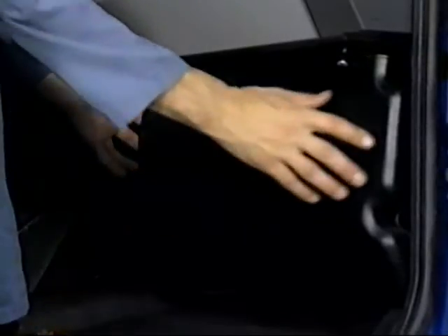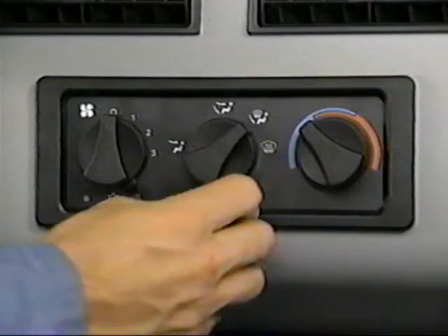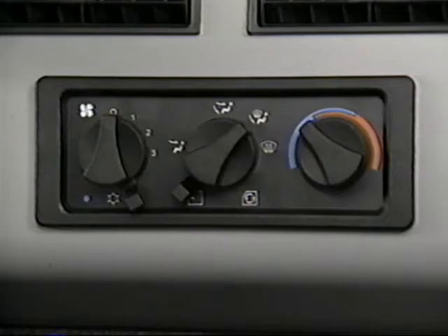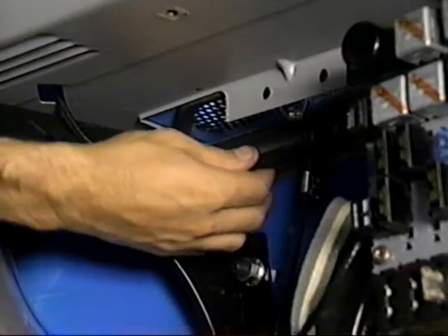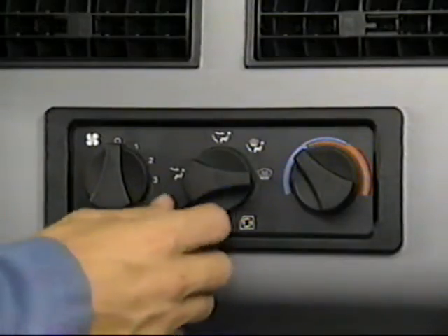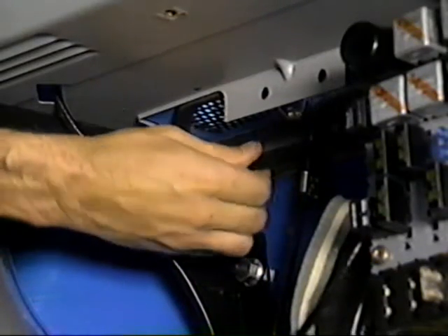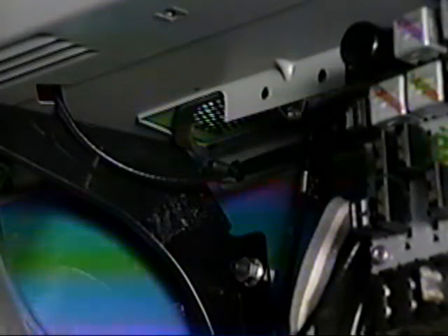To adjust the fresh air recirculation door cable, remove the kick panel under the dashboard on the passenger side for access to the door. Move the air selection switch to the fresh air position. Adjust the turnbuckle under the dashboard until the door snaps into the horizontal position and closes off the opening to the cab. Move the lever to the recirculating position and make sure the door snaps open. If necessary, readjust the turnbuckle so the door is in the correct position for each control lever setting.